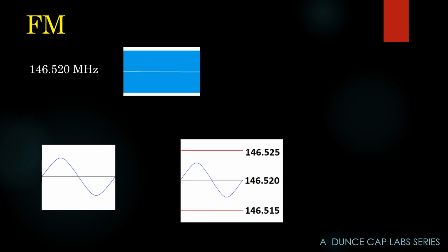When we modulate it, notice how the frequency swings up 2.5 kilohertz, then it comes back down, then it swings down 2.5 kilohertz, then it comes right back where it started. We literally are steering the frequency back and forth and back and forth. We make it swing back and forth to quote unquote look like the original audio signal.